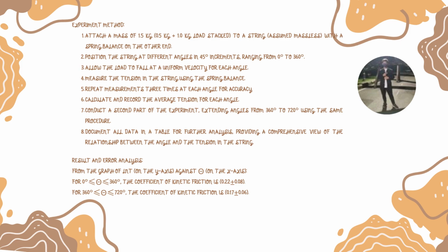From the graph of ln T on the y-axis against theta on the x-axis, the coefficient of kinetic friction was determined. For the range 0 degrees less than or equal to theta less than or equal to 360 degrees, the coefficient of kinetic friction was found to be 0.22 plus or minus 0.08.